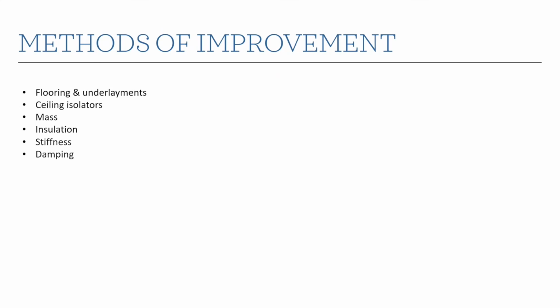Okay, the last two things I don't have examples of because they can be a little bit more complicated. So one is stiffness. If we're looking at a lightweight joist floor, it can be fairly flexible. And if it's flexible, when you walk on it, it's easy for it to bounce and move and create sound. And if we stiffen it, often it can perform better. That really gets more into structural considerations and things like that. So know that that's a tool that can be used, but probably something to consult a structural engineer and an